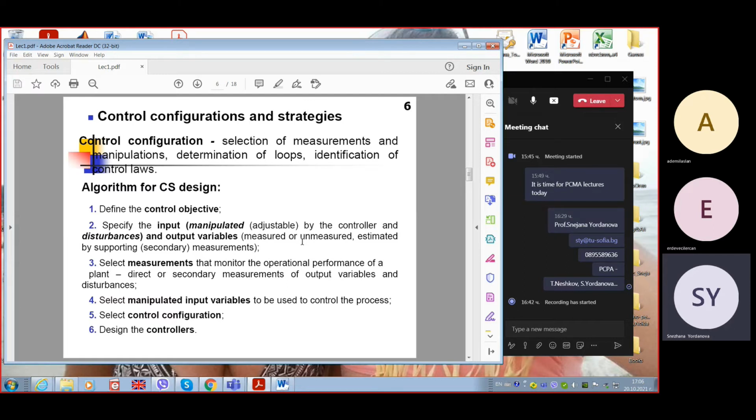The cold ends should be kept at 0 degrees, so in melting ice inserted, but between the two ends there is a small voltage in millivolts when the connected part is inserted in the hot medium, whose temperature we want to measure.